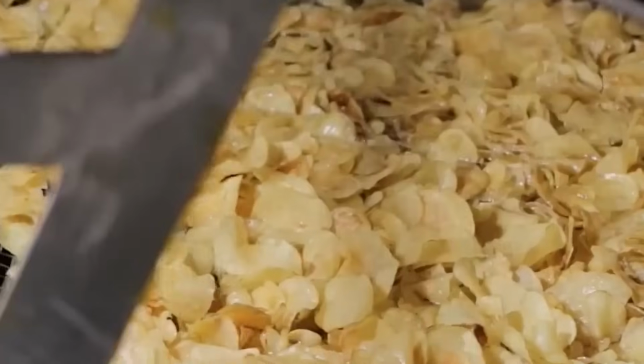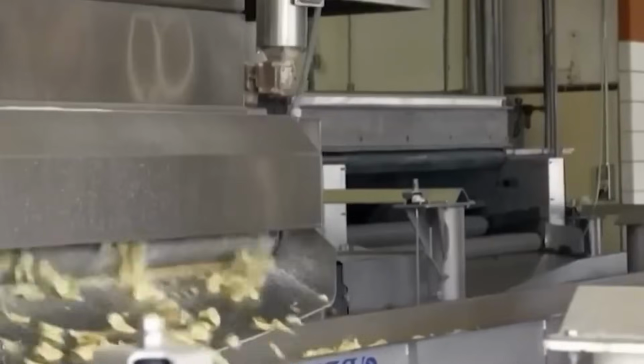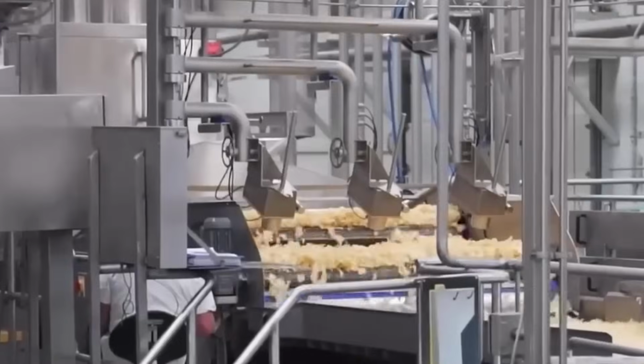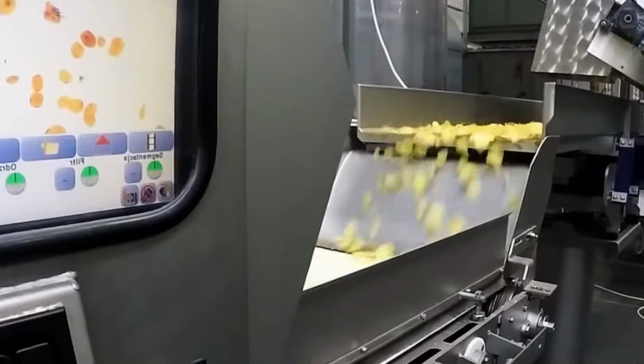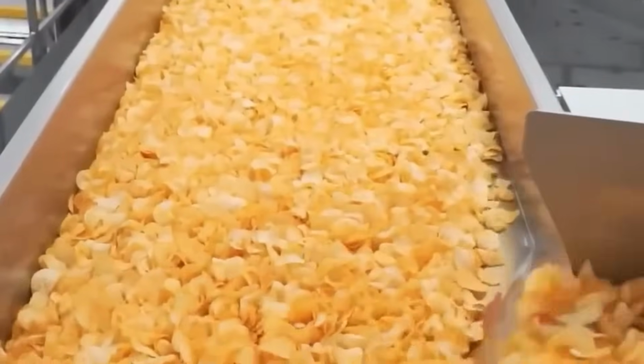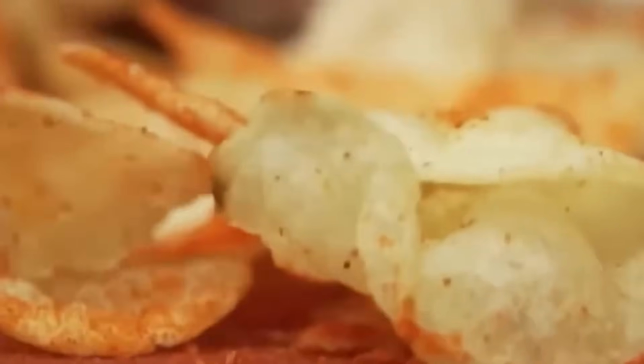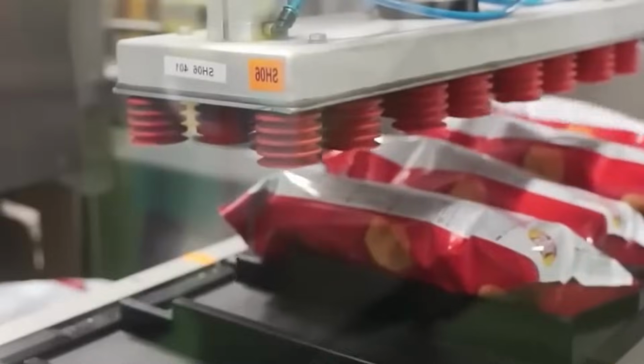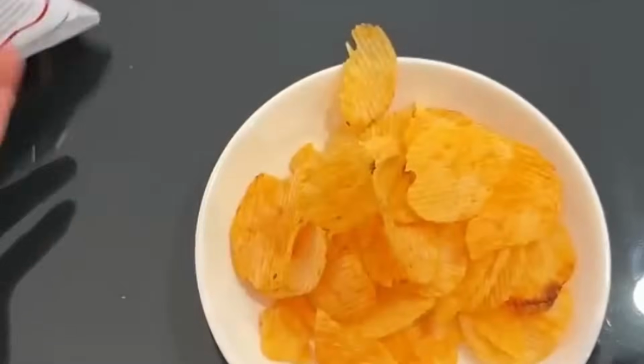In abrasive peeling, the tubers are rotated inside a drum lined with abrasive surfaces that scrape the skin off while minimizing flesh loss. After peeling, potatoes are rinsed again to remove any residual skin particles. Peeled potatoes are conveyed via stainless steel belts to slicing machines. These are centrifugal slicers equipped with rotating impellers that force each potato against razor-sharp blades mounted on a rotating head. Blade thickness is adjustable down to tenths of a millimeter to produce slices typically between 1.2 and 1.5 millimeters thick.